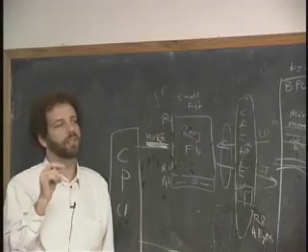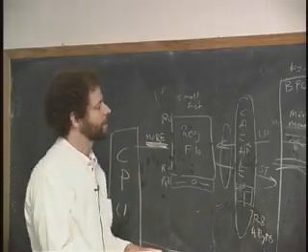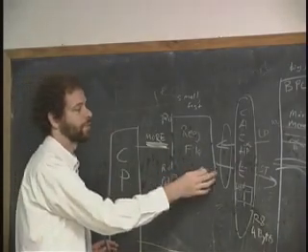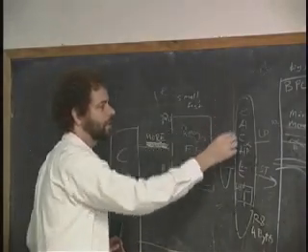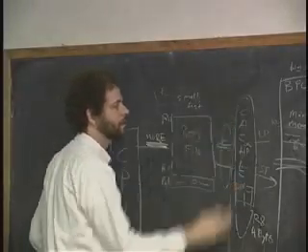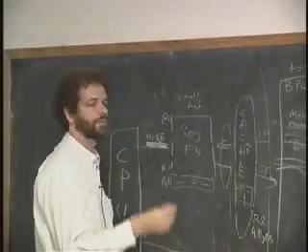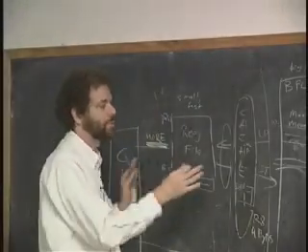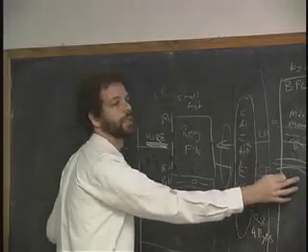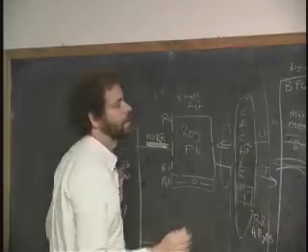The last thing that I was going to say is that typically the boundary of the integrated circuit, so the processor is on an integrated circuit, the register files are on the same chip, and then either the L1 cache is on the same chip and the L2 cache is not, or for newest chips, both of them are, and the boundary of the chip is there. And it turns out that physically, as soon as you get off of the chip, the one chip that's going to hold all this stuff, and go to a set of wires to another chip, everything slows down a great deal, because you need to drive those wires.